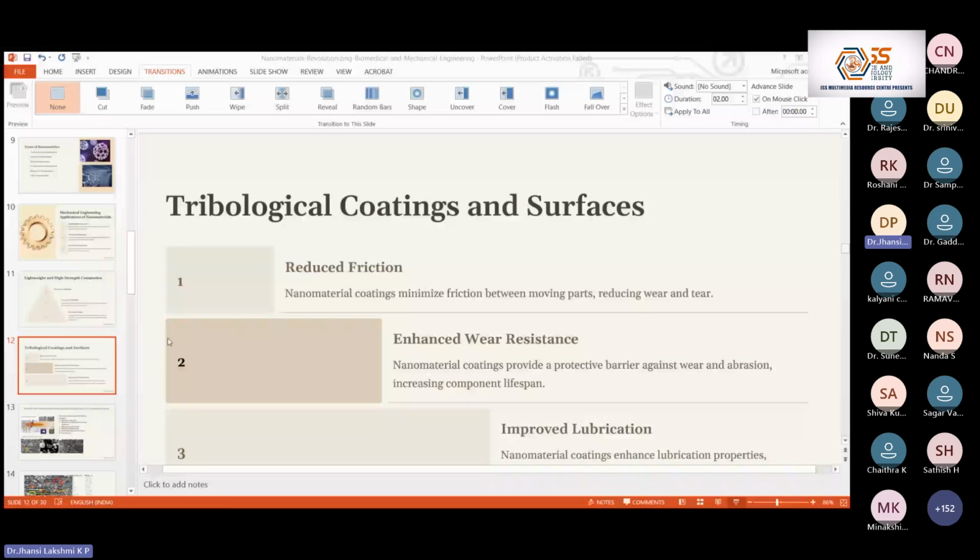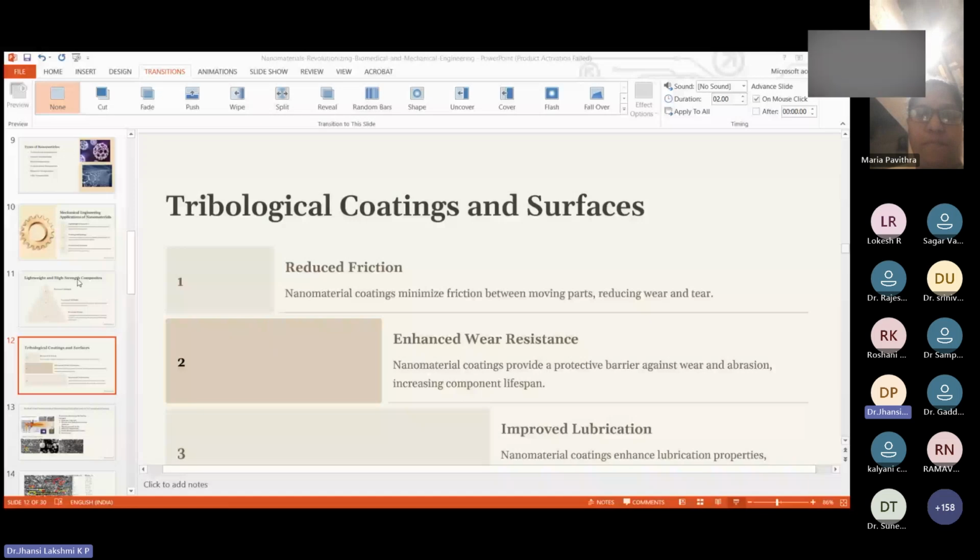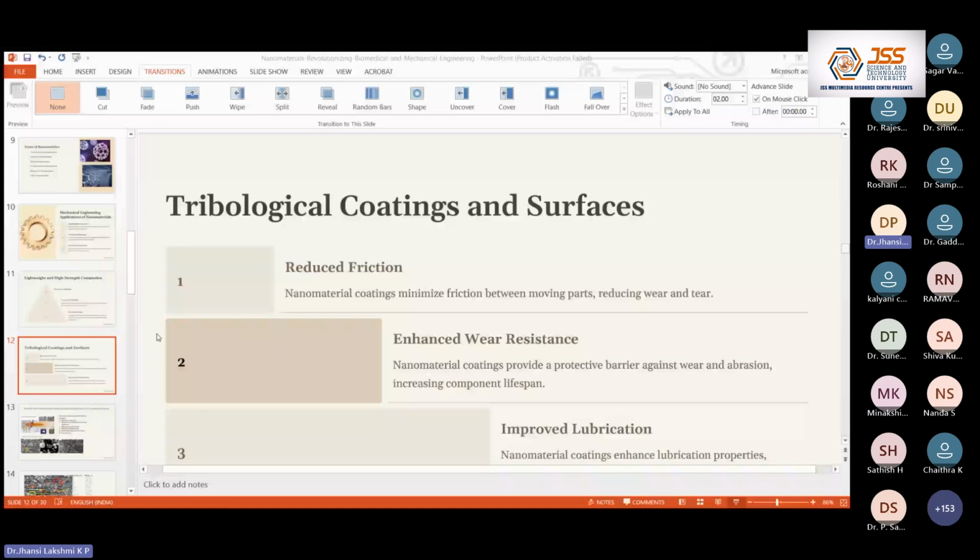We have different thermal spray processes like HVOF, that is high velocity oxygen fuel coating process, the detonation gun process, and HVAF. There are so many thermal spray processes. Among those, the researcher has chosen the plasma spray process. Maybe the reason is that in the plasma spray process, the standoff distance between the substrate and the jet is very small, so that the escaping of the particles will not be there.